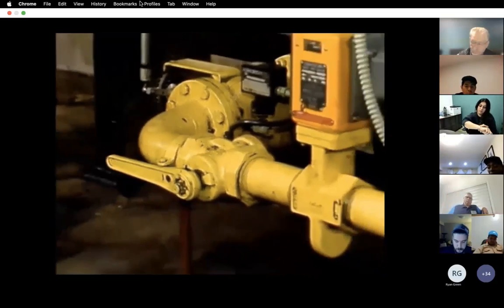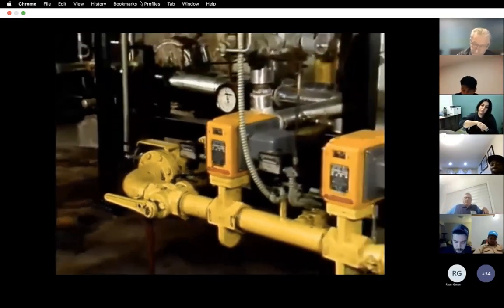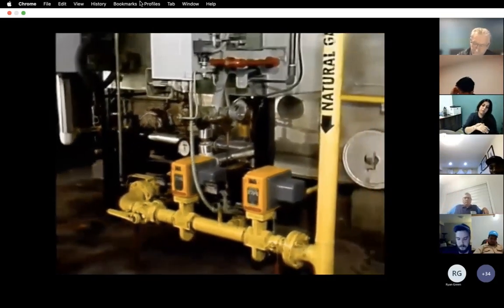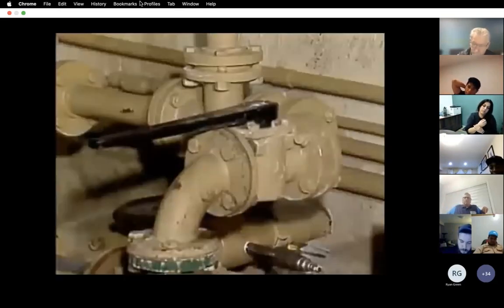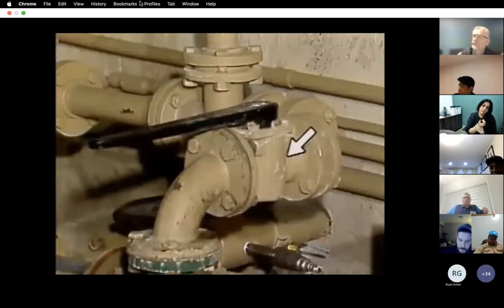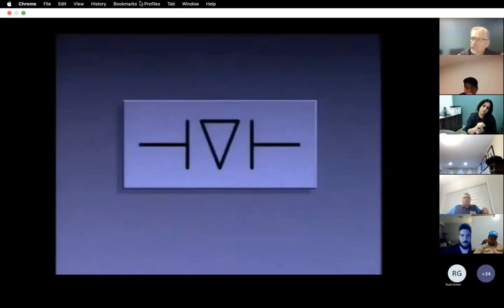Plug valves are generally used for on-off purposes in situations that require quick valve operation and a tight shutoff, such as in this gas line. Plug valves can usually be recognized by their cylindrically shaped midsection and flat bottom. On a piping diagram, the symbol for a plug valve generally looks like this. If the symbol looks like this or has the letters NO beside it, then the plug valve is normally open. If the symbol is filled in or has the letters NC beside it, then the valve is normally closed.